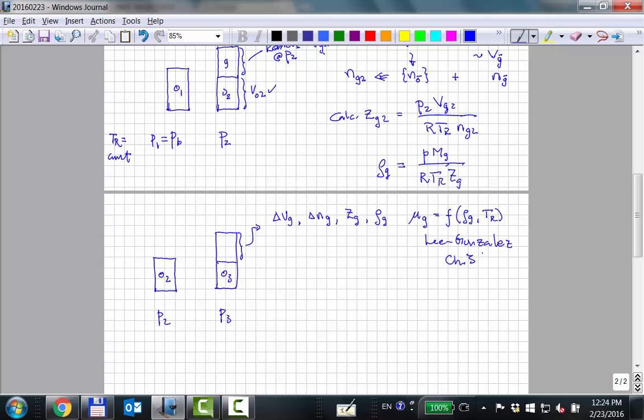It's not particularly important that you read it or look at it, but that's typically the equation that's used by most laboratories. And they don't measure gas viscosity because, well, first it can be well predicted with these correlations within maybe 5% normally. But the equipment for measuring gas viscosities at high pressures is not particularly simple equipment. So they basically just don't do it. They don't measure those viscosities. So it's calculated. So this is all the gas properties here.